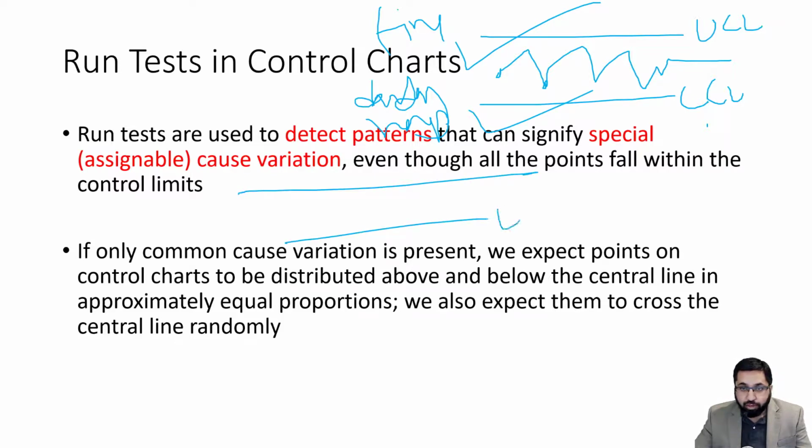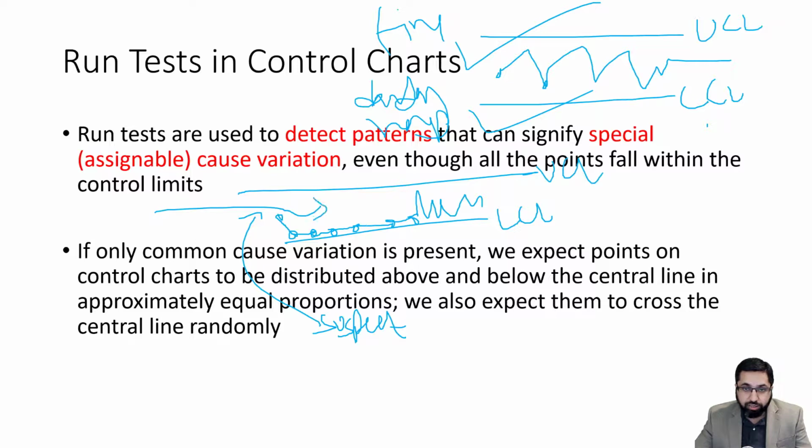If you have the control limits, LCL and UCL, and your data shows a pattern, let's say it goes down towards the lower limit and just lives there, sample after sample, getting data very close to the lower control limit, this is highly suspect behavior. If it's common cause variation, which is random variation, it should be moving up and down randomly between the control limits. It should not be just hugging the lower control limit, right? You should ask the question, what's up?